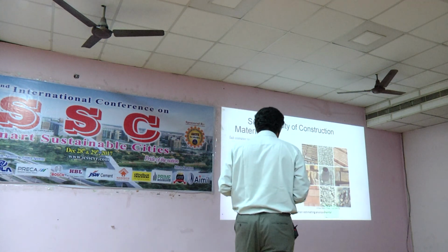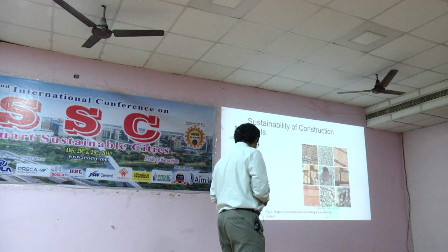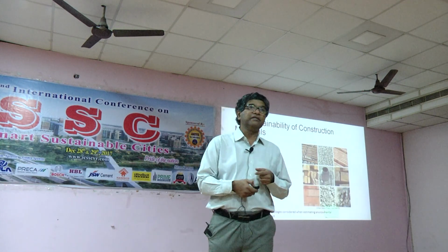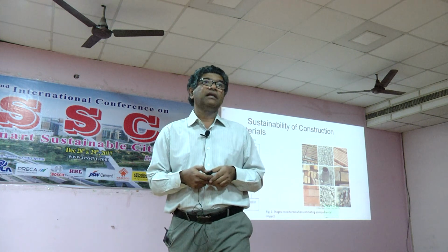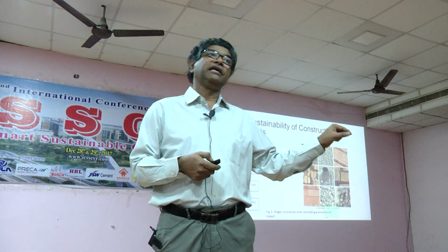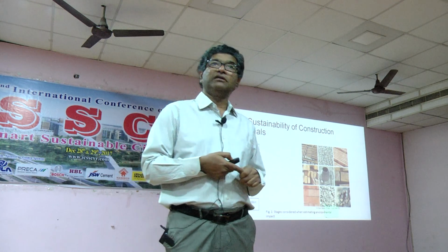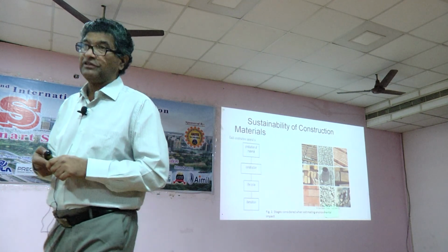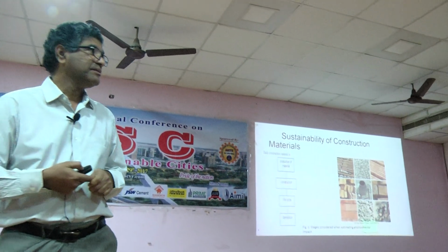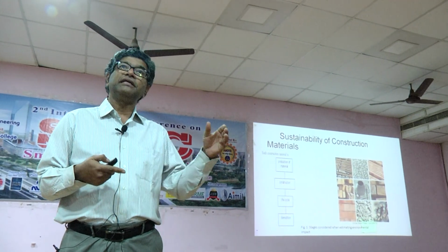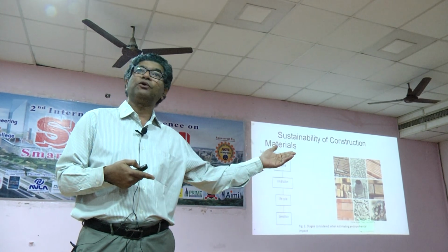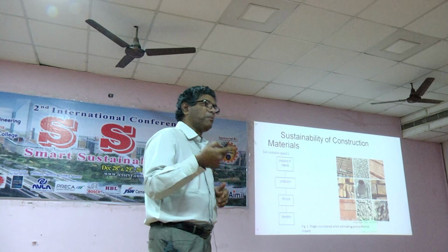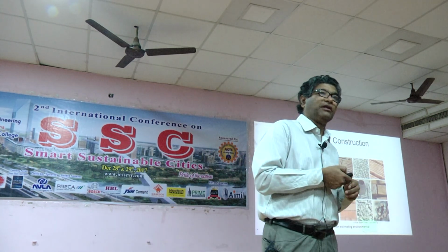And then what is its life cycle, right? This is the biggest problem that people always keep asking me whenever I design a building. I say that the life of the building in my design brief report is 50 years. People say it's not going to last for 100 years. But I say, gentlemen, there is a maintenance factor. If you keep maintaining your building, 50 will go to 100. Otherwise, 50 will even come down also. So you need to maintain your building at some regular intervals, right?